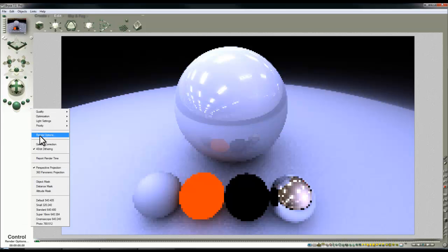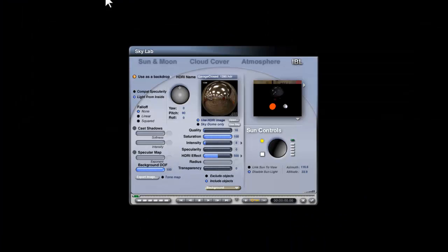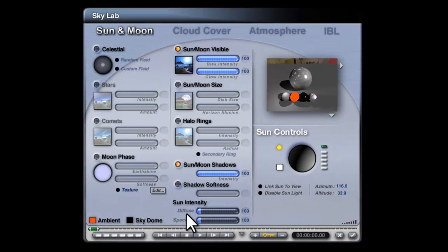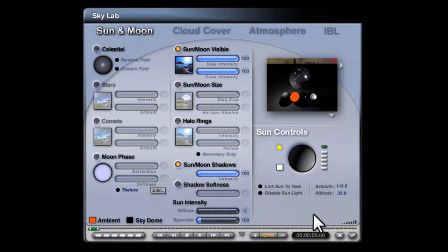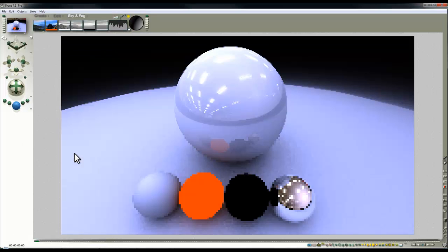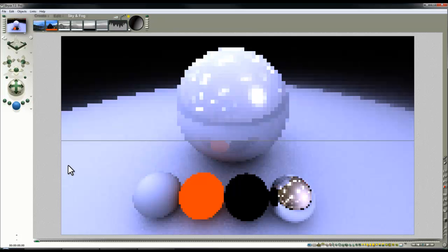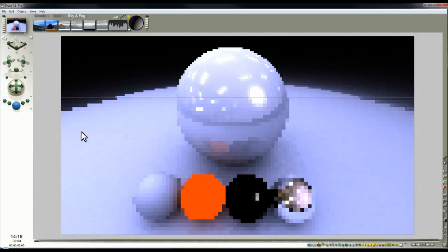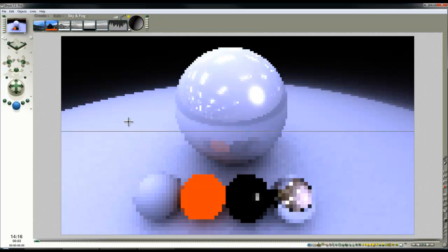If you introduce a direct light source, which I can do now quite easily by re-enabling the sun, and I'll just turn off diffuse, so we just wanted this for specular highlight effects, then I'll just check out of that and we'll see how that's affecting the render time. It might not be too bad, it just depends how much specular's in. 14 minutes, so everything comes at a price, but as you can see, these shadow regions are very well simulated.